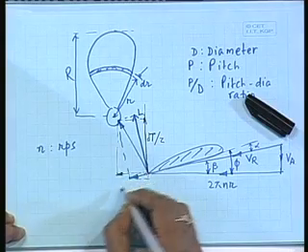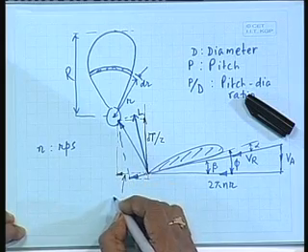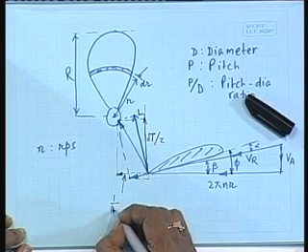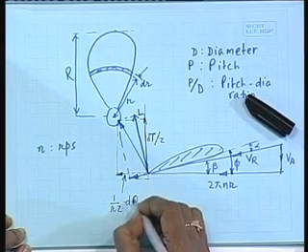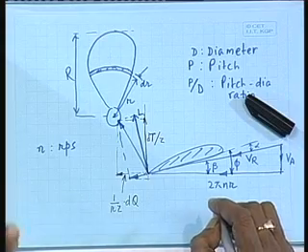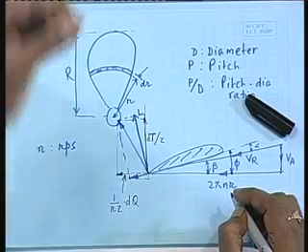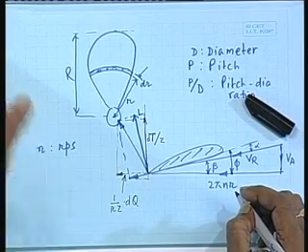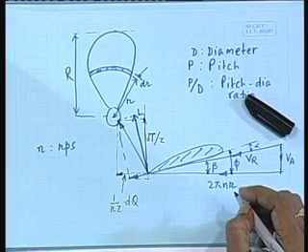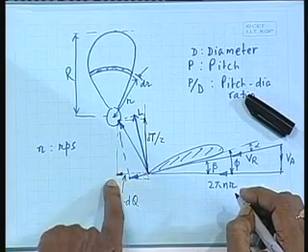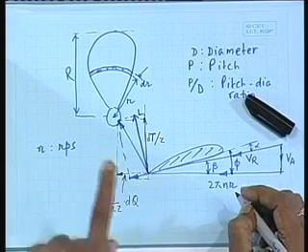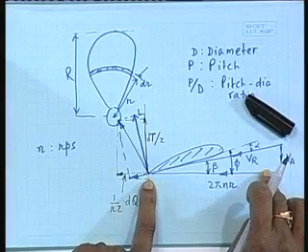So, elemental torque will be, if dq was the torque due to all the elements, then 1 divided by z dq is the torque due to each element, and if I divide that by r, I get the tangential force. Remember, I am doing a force diagram here, I am not doing a moment diagram. Torque is a moment. So, I must convert it to tangential force. Which is the tangential direction? This is the tangential direction.